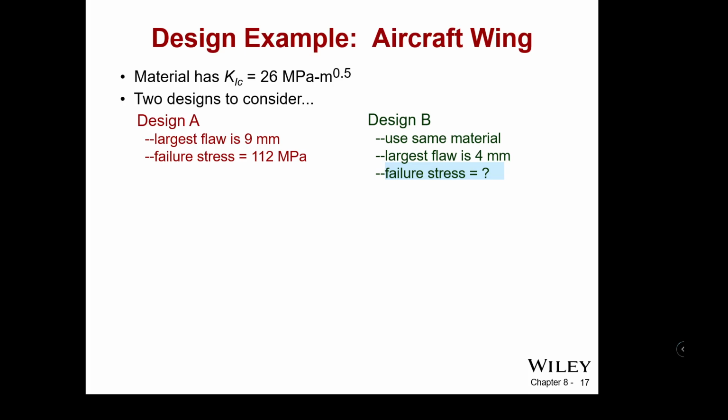So for something like an aircraft wing, again, something that lives are relying on, where cracks are exceedingly bad and could lead to imminent death, we want to pay very careful attention. So the material has a Kc of 26 megapascals meters, square root of meters. It's a kind of confusing unit, but it's again a constant to help us relate materials to another material.